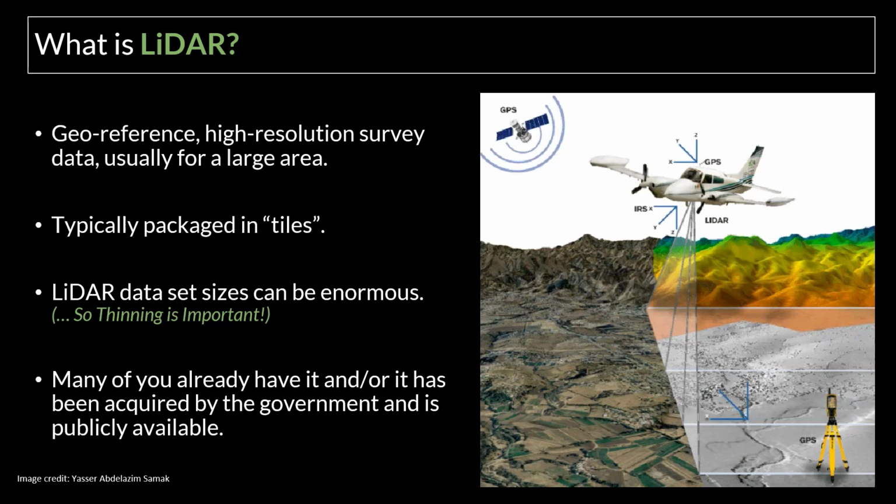Rule of thumb, when working inside of our software, we try to keep your modeled points to under 10 million. It sounds like a lot, but we've seen LiDAR data sets up in the gigabytes of size, which ends up being, I don't know, about 100 million points. So you're going to have a whole bunch of slowdowns if you're working with one of these extremely large sets. So yeah, making sure you're leveraging those thinning tools.